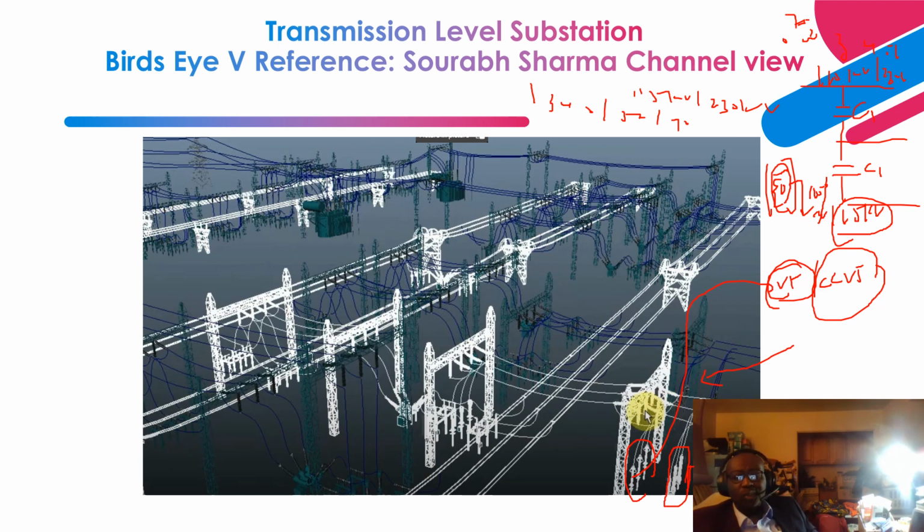So if I have my transmission line coming in here at 115 kV, the goal is to achieve, let's say, 2 kV or 10 kV on this section. Then I can feed this to an inductive transformer immersed in oil that steps the voltage down from 2 kV to 69 volts line to neutral, or 115 volts line to line, to be used by our protective relay or metering elements.